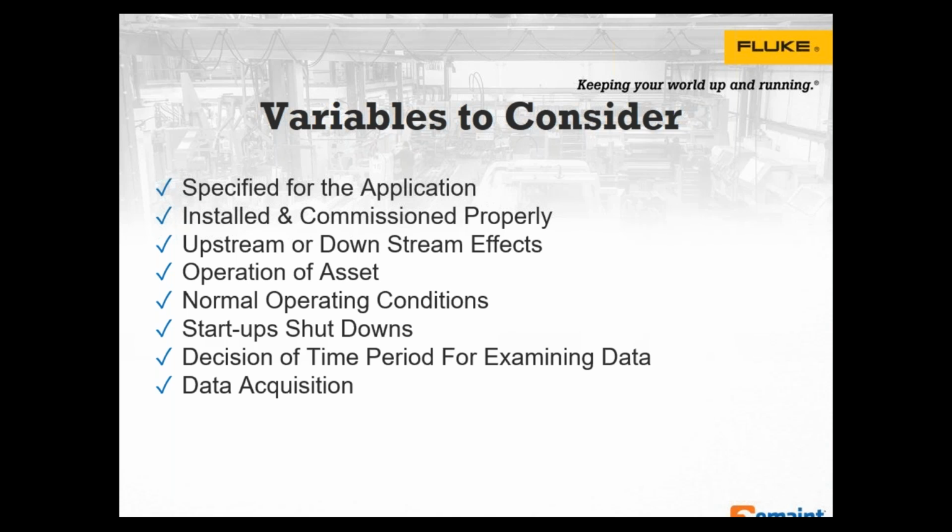Sometimes they may want to average up to 30 readings. What I'm talking about is a boxcar type of averaging, first in, first out. If you have 30 values of 5, and the next value that comes in is a 6, and then you got another value of 6 coming in, you're throwing out the 5s, your average is starting to change, and you can start seeing your trend change. But really, does the user know that what they're looking at is a smoothed or averaged output?